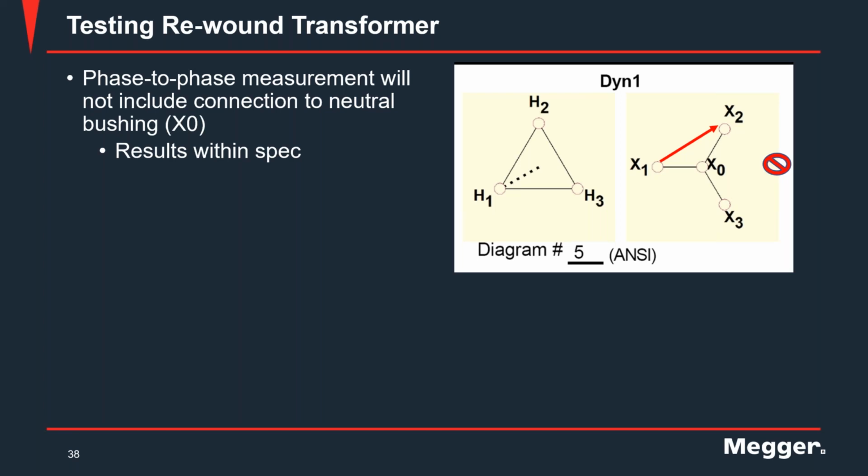Thank you, Samir. While I have you, can I also ask this next question over to you? In the case of a deviation greater than 2% in the measurement of the winding resistance, given the rest of the tests are fine, and the results of the physicochemical and dissolved gas oil analysis are fine, to what can we attribute this difference? That's a great question. I'm sure many of you might find yourself in that situation where your winding resistances are slightly beyond 2%, but your oil analysis, before the test or right when you're getting ready to reprocess the oil, all looks okay, as expected. It's not that the transformer was under a fault or anything, but you're still getting that slight mismatch.